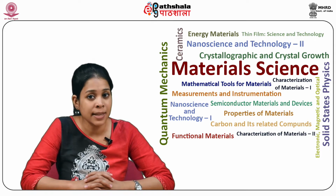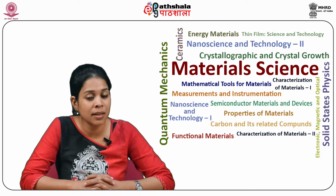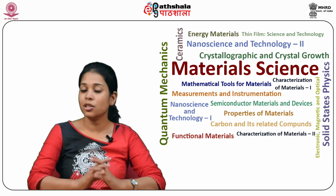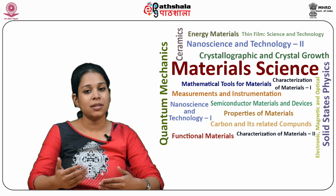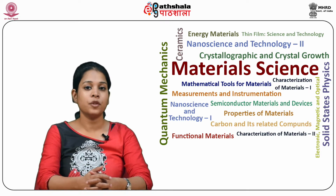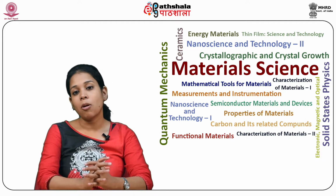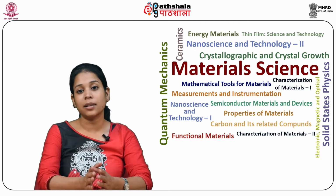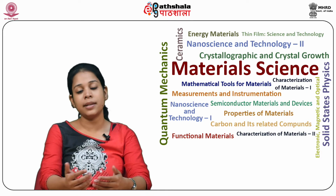Having said that, it must be borne in mind that some materials like silicon, that is Si, are covalently bonded and the orbitals do not have spherical symmetry, and as a result, the dielectric constant can be higher. For example, silicon has about 12. So for electronic polarization, epsilon r is also equal to n square, and hence if one knows the refractive index, it will be very easy to check the values calculated.